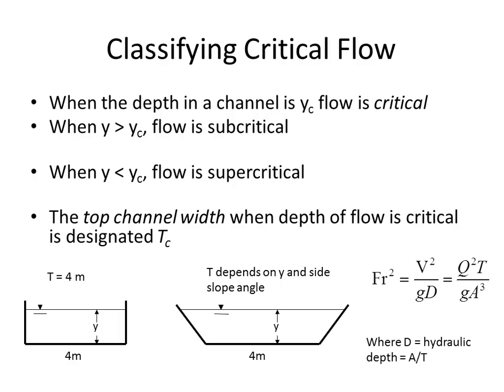And you need to know that, because one of the ways you can calculate the Froude number is taking into account the flow rate, the top width, the cross-sectional area, and g. So both of these are ways that you can calculate the Froude number. And you've seen this one before. You found the Froude number was the square root of it.